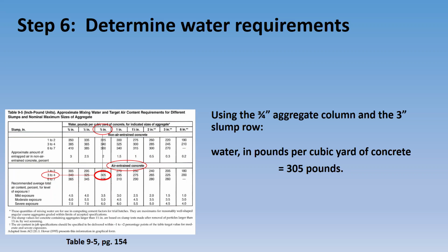And look at the title of this table. This is water in pounds per cubic yard of concrete. So we need 305 pounds of water in our theoretical yard mix design.